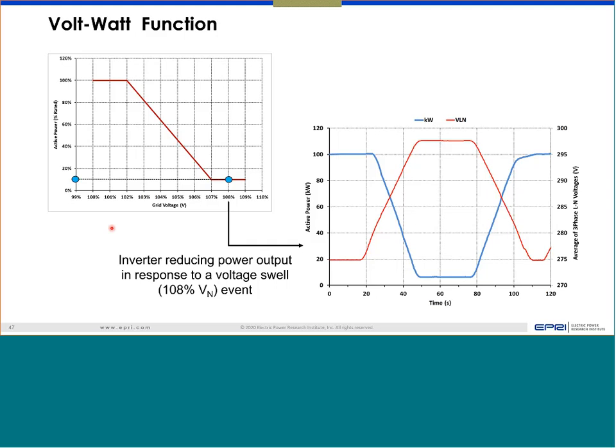Does VAR injection or absorption depend on irradiance? The answer is no. As long as the inverter control board is operating, like it has some power to run its DSP board or microcontroller board, it can produce reactive power. However, most of the commercial inverters available in the market or installed in the field are designed to go into sleep mode during sunset.